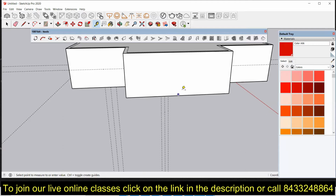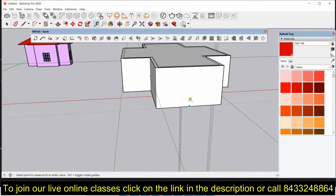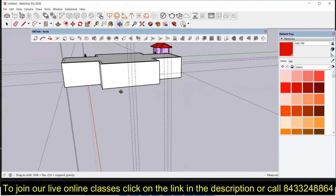Now again, just try to make one more over here at 2 feet 6 inches, so that I can show you the different types of windows that you can create. Okay, then you also need a distance, so let's take the midpoint and then take an offset of 2 feet 6 inches. That is good over here. Okay, so this way you have the space for the windows.